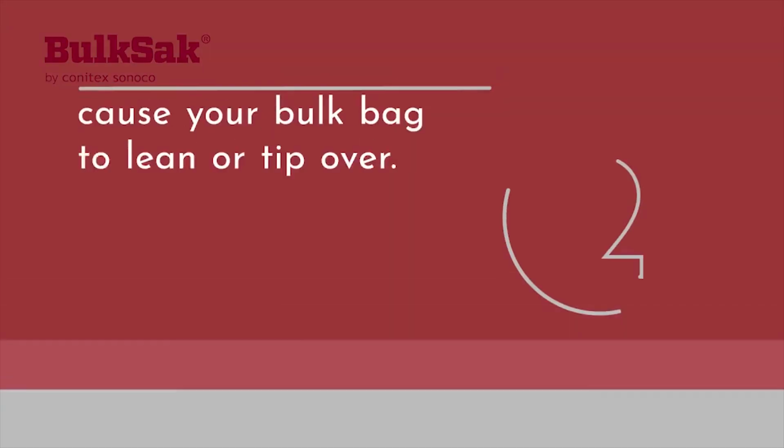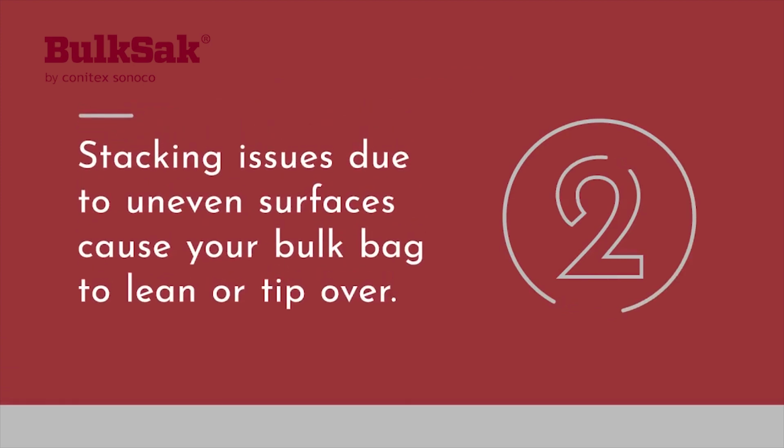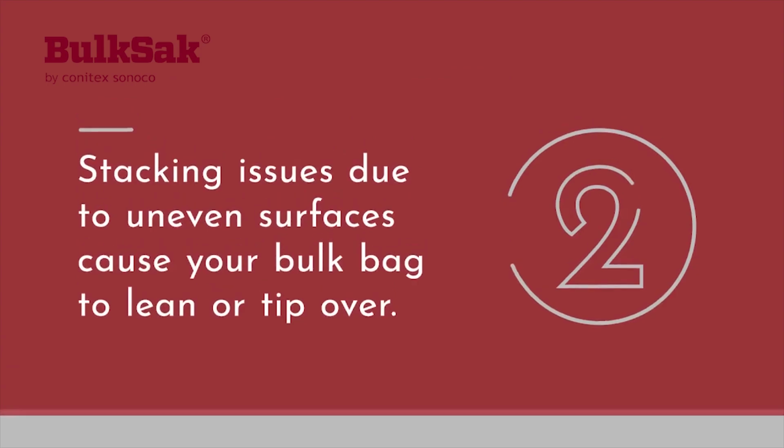Secondly, the stacking or stability of the FIBC. Without properly getting into the corners of the bag, it creates an uneven surface at the top. Any bag stacked on this surface will start leaning and in some cases fall over, creating a very dangerous environment for anybody having to handle the bags.